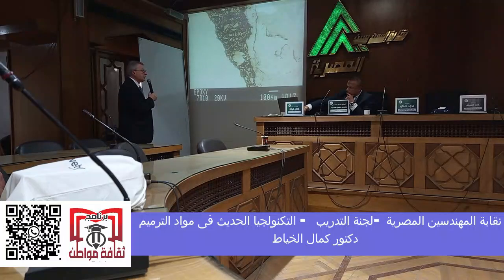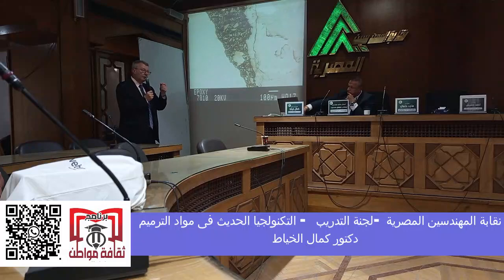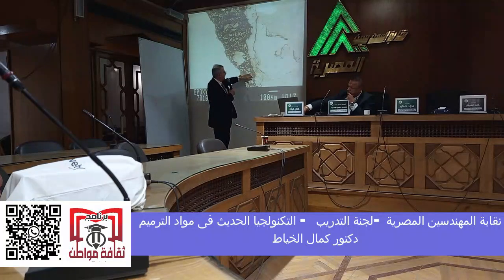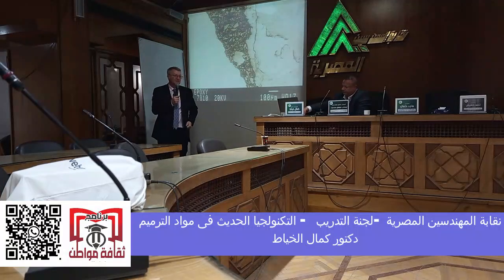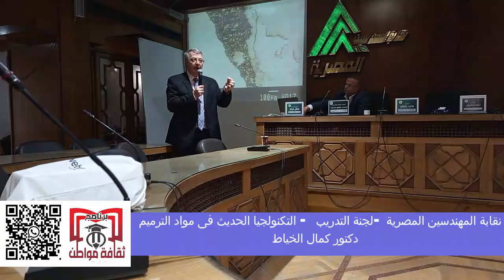One thing we noticed when we put it under a microscope is that the epoxy has a filler. Epoxies, even the epoxy resins, are not just pure polymers, they have some fillers, like limestone, small fillers. On one side here, the white is existing concrete with a crack, and in between you have the epoxy. Then you get to a point where the crack width is very small, and if you have some fillers that are blocking, then you don't have any more penetration. That's why it's very important to control the maximum size of any inclusion when you are grouting, otherwise you're going to block.